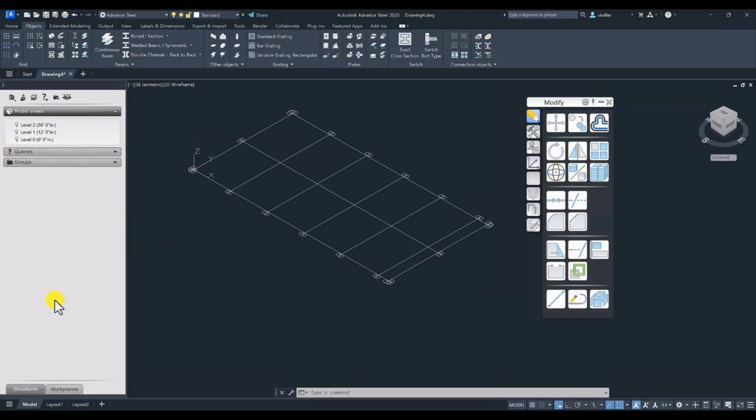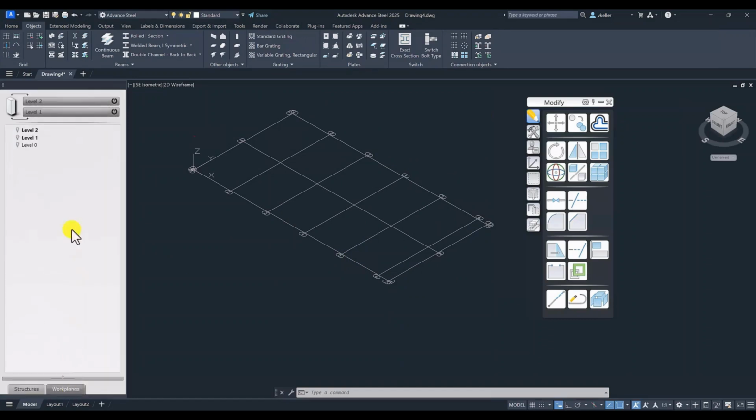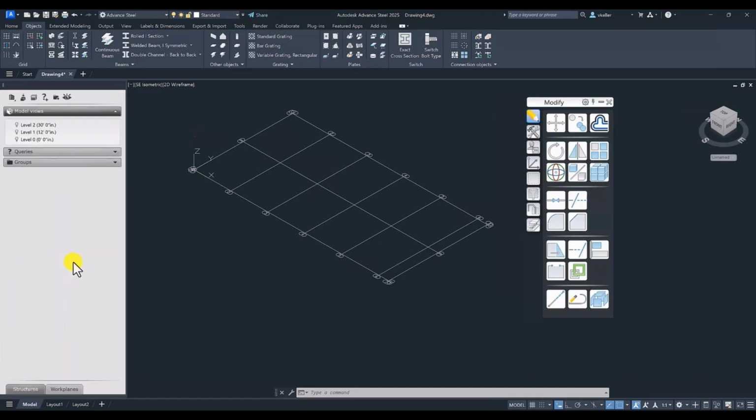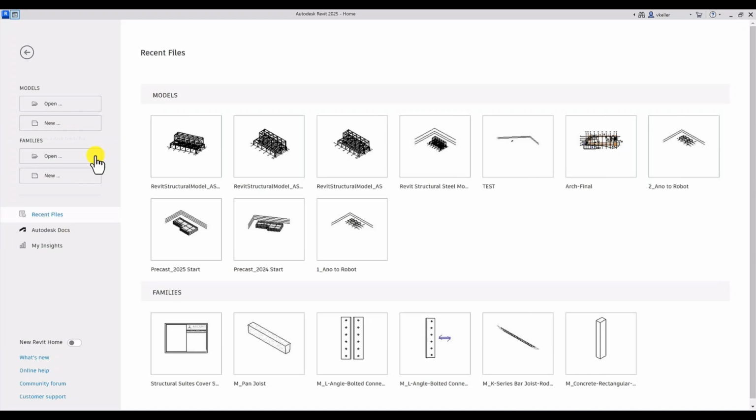Now there's another part of the Explorer, if I pick on a tab down there called Work Planes. When I'm drawing, I can draw according to a work plane. So if I were to drop in columns, I would choose the 2 work planes to put them on, and that would be the height of that column. Yeah, and this is how I begin. I save it out.